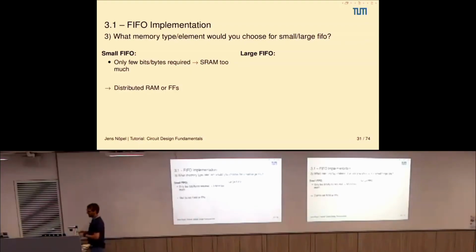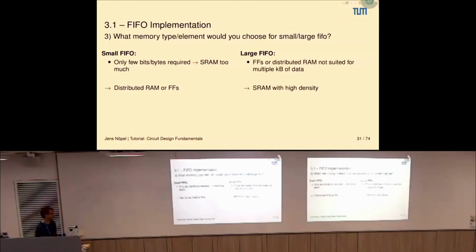There's also something called distributed RAM, but I wouldn't go into that very much, just be aware of it. We also talked about LUTRAMs already a little bit. So this relates to using LUTRAMs for this case, but it's okay if you just remember we use flip-flops in this scenario. And for the large FIFO, we use SRAM because it allows us to store multiple kilobytes of data.